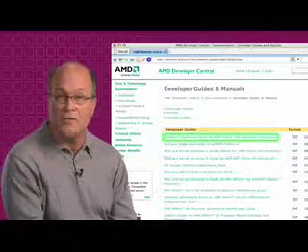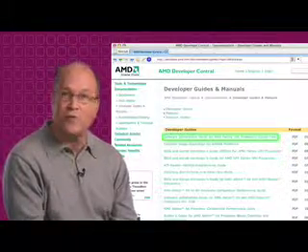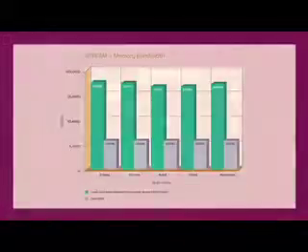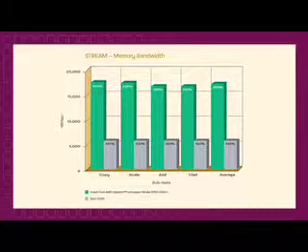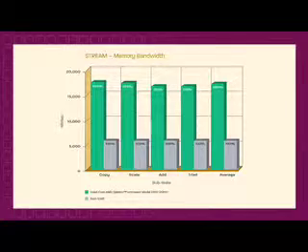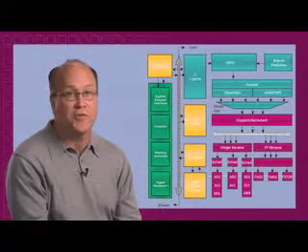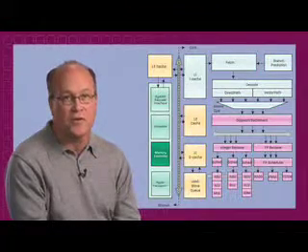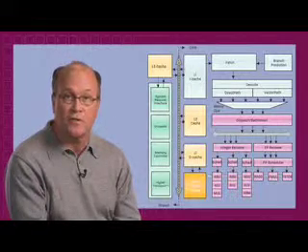Much of the content is based on that document, but here we'll expand on some concepts and show some concrete examples. The recommendations in this series are intended to help you improve the performance of software applications on our new processor family. You'll learn about the microarchitecture of the third generation Opteron processor, how we sped up memory access using prefetch, HyperTransport technology, and out-of-order memory loads.